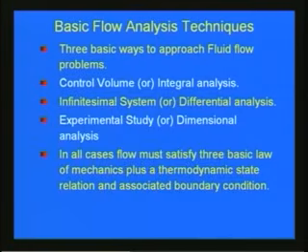The second approach is called differential analysis or infinitesimal system analysis. Here, with respect to a particular point, we look at how important fluid properties like pressure and velocity vary with respect to x, y, z. That means a particular point is concerned. That kind of analysis is called differential analysis, like del u by del x, del u by del y, or del u by del z. So, that is called a differential analysis.